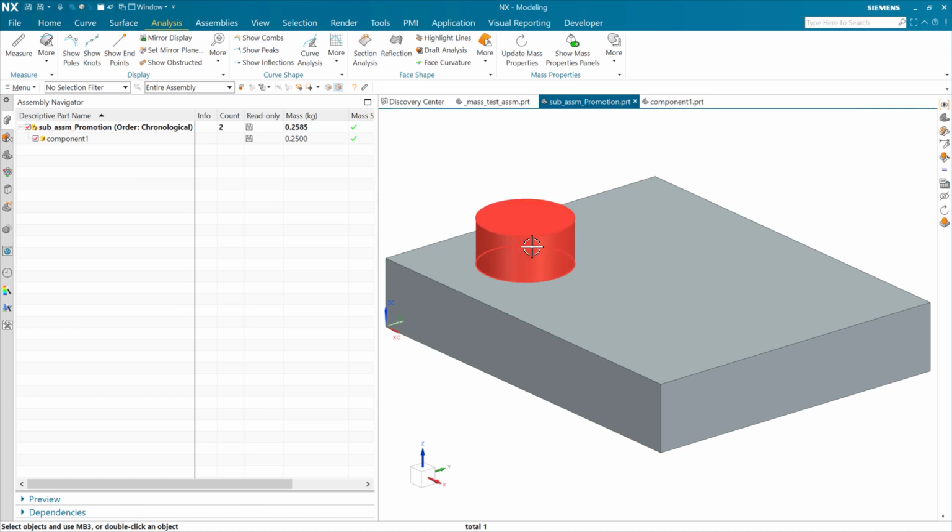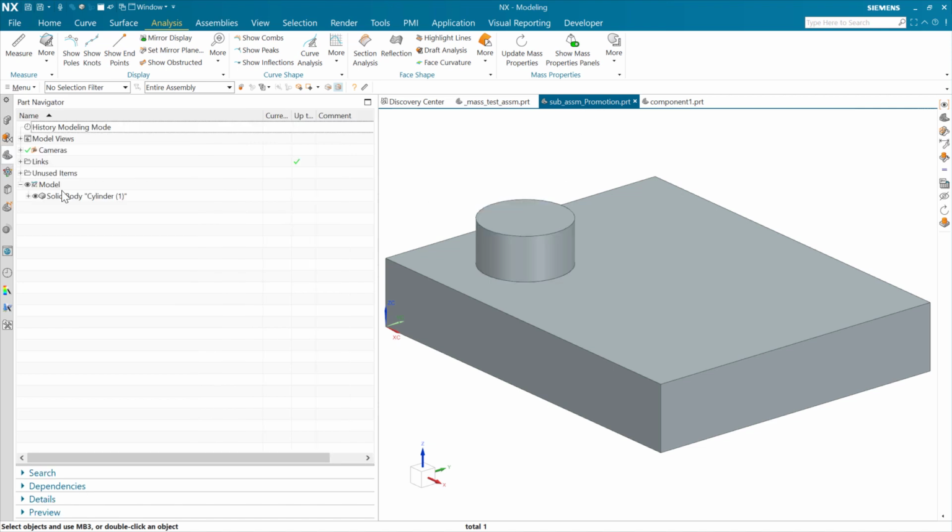At the assembly level, we've got a little bit of extra geometry here, right? Here I've got a promote body feature. Again, this is going to copy the body upward into the parent assembly from the component. The cylinders here at this assembly level, and then we might combine those, for instance, in a subsequent operation.